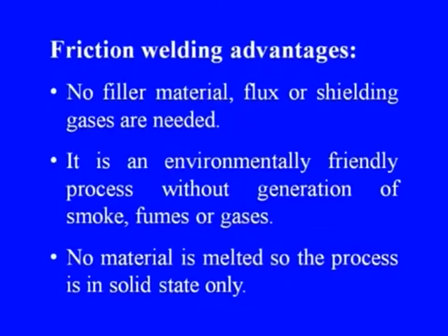Then flux, as we know, managing the flux on the welding zone itself needs some other arrangements. It is an environment friendly process without generation of smoke, fumes and gases that I have already indicated. No material is melted, so the process is in solid state only.